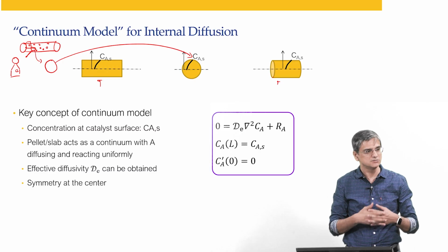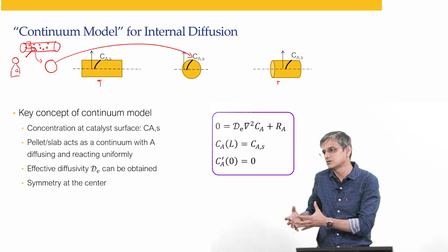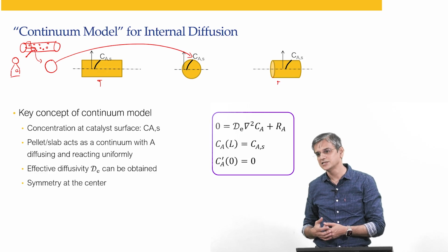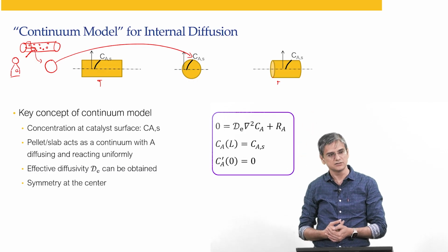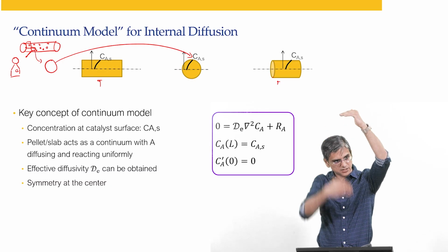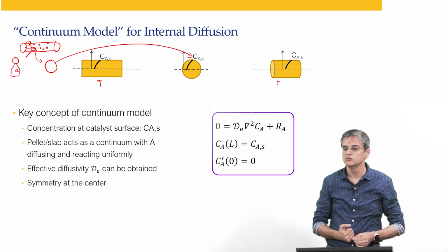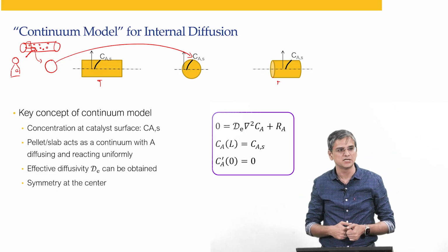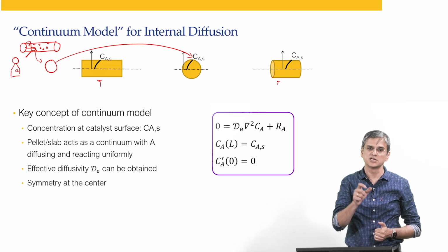The first concept that comes is processing of the material. If you cannot process the catalyst to make a particular size and shape, you will not be able to do it. The next thing that comes is structural stability. Let us say we have a large reactor and you pack the reactor with the catalyst pellet. The pellet over here has to bear the entire weight. Because of the weight, if the pellet gets crushed, you are not going to do that. Either we will make multiple plates in the reactor or we will make pellets in a different way, and that becomes the governing factor rather than CRE.